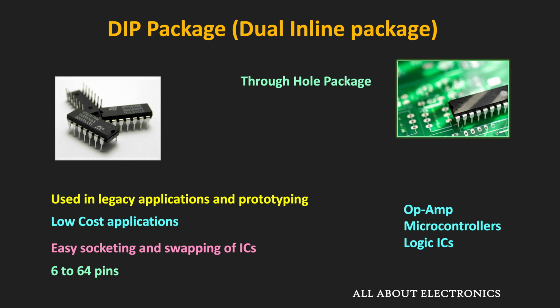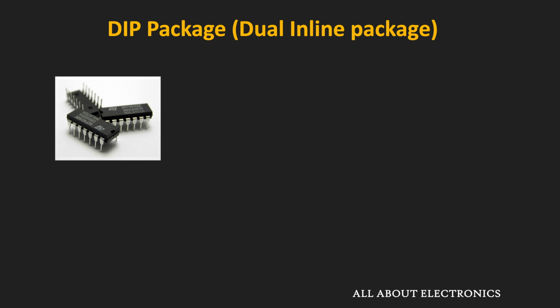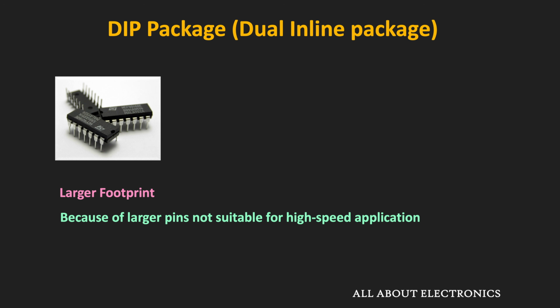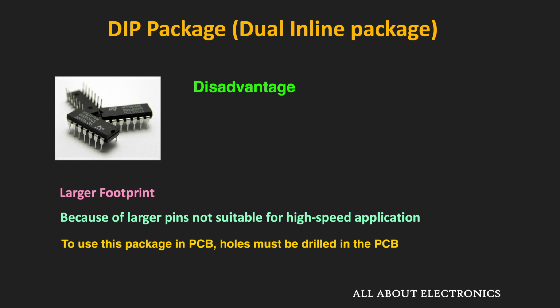Now the main disadvantage of this DIP package is that the overall footprint of the package is larger than other packages. And as the pins are larger and longer, the lead inductance is also higher. Because of that, the ICs available in this DIP package are not suitable for high-speed applications. And not only that, to use this package with PCBs, we also need to make holes in the PCBs. So these are a few disadvantages of the DIP package.